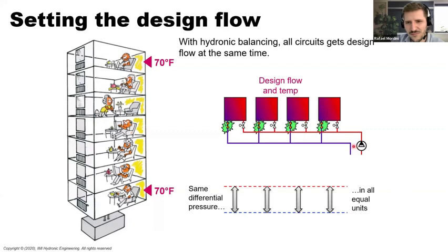If you have an excess of available pressure here, we create some pressure drop on this valve. This valve will be responsible for absorbing any excess. And now they all will receive the same available pressure, and if they are identical, they will receive the same flow rate as well. And everybody's happy here. No one is sweating and no one is freezing cold.